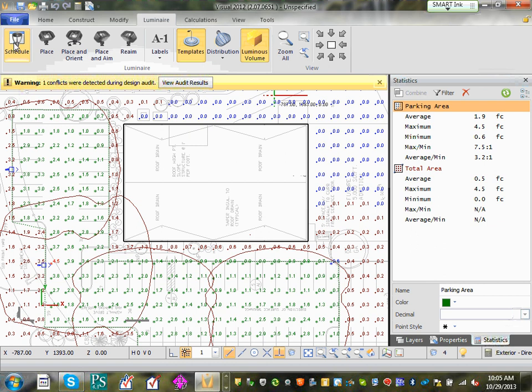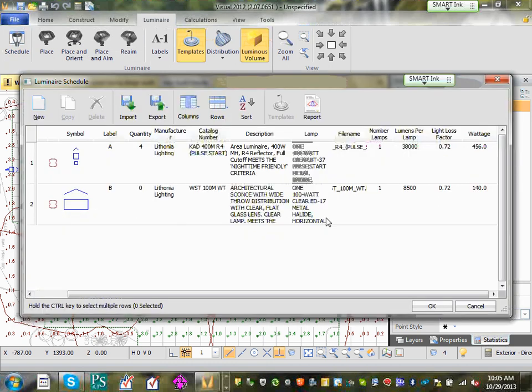So everyone's got that fixture. Did you change the size factor? For wall packs, no. I would just look at it and put them on there. If they look too small, go in and bump that up, because if you use 3 on the wall, they just look enormous. It won't do anything to the light levels, it's just how it appears on the screen.